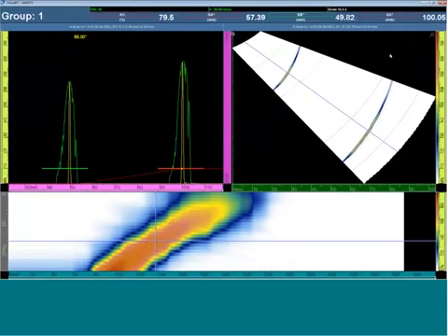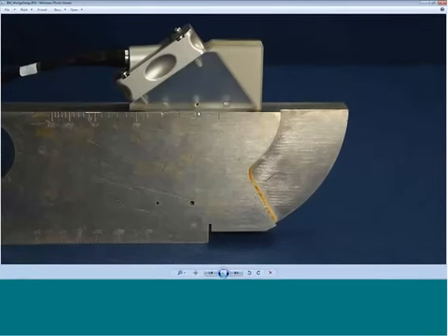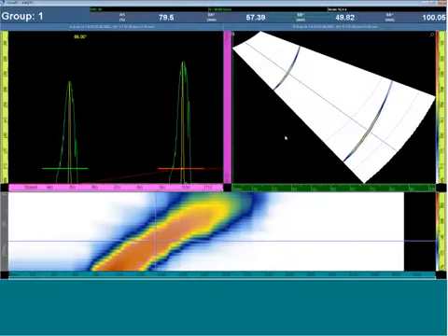And we can see here that in the phased array sector scan using the wedge delay calibrator that we're going to learn in the upcoming section, and using a series of checks that we've already discussed for every individual A-scan, and in this case the 55 degree, we have accurate sound path, wedge delay, velocity, and linearity across the whole array.